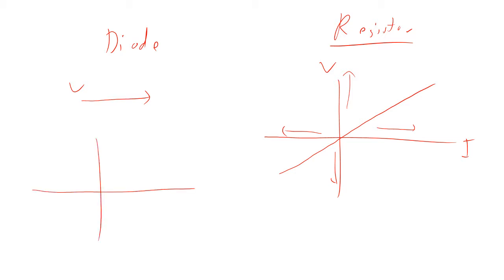With a diode, I have voltage, I have current, so what would happen is if the voltage went positive, then the current would shoot up like that. On the other hand, if the voltage went negative, the current would drop straight down; no matter how negative the voltage, I'd get either little or no current. So that pretty much makes this like a one-way valve for electricity: if the voltage is in one direction, current flows, and if the voltage is in the other direction, current doesn't flow.